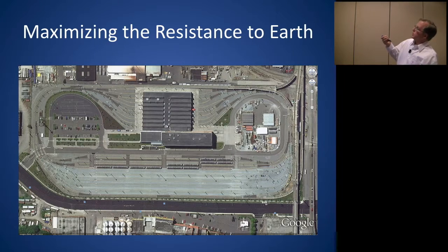We also put insulators at what they call yard leads here at these turnouts where it comes off the main line and goes into the yard. There's another one right here. Because, again, parallel resistance there. You've got a lot of parallel tracks in here, so even though individual tracks are high, the overall parallel resistance is pretty low.